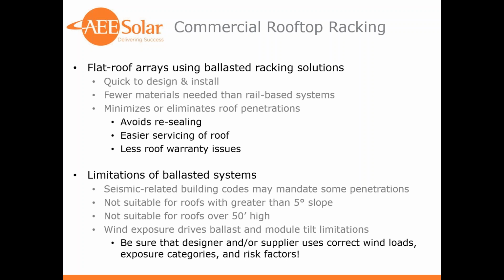The wind exposure, which is one reason for the 50-foot high building, it's probably the tallest building within a couple miles. It drives the ballasting and tilt module limitations. Higher tilts need more ballasting, need more penetrations. Lower tilts need less. So be sure to ask that we have the correct information, that all the wind loads are correctly identified, the exposure categories are identified, the building risk factors are correct.